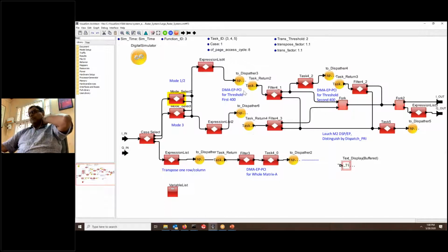Other things, for example, here, the data size is 800 bytes, but I'm taking 400 bytes and processing them. Why is that? That way, I can pipeline my system better, so I need less processing capacity, and faster memory accesses, things like that. Of course, you have the other flows having different data sizes and different requirements, but the top